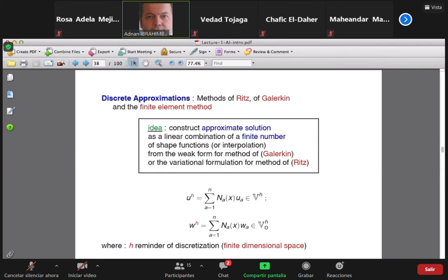But the idea is really that you need a guarantee that the solution could be achieved. So the reason why the finite element actually works at the end is the following. If the solution to your problem in terms of mathematics is a so-called analytical function, that means you can always develop the value of this function by using a Taylor series, using the value at a particular point of the function, its first derivative, second derivative, and so on and so forth, then you're sure when you use polynomials, basically you come down to using the Taylor series directly. And then you're sure that you can converge intuitively.